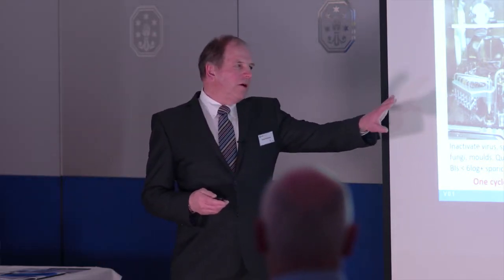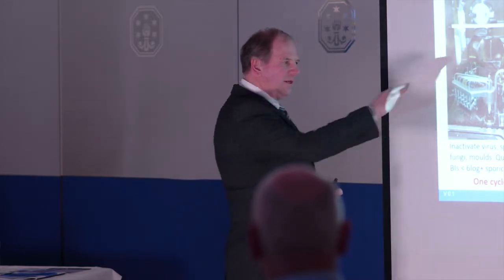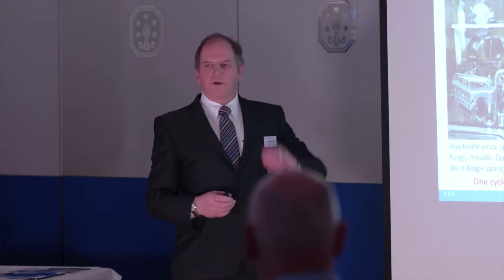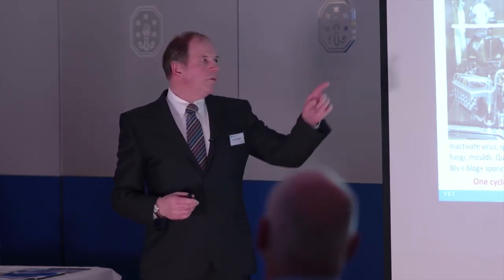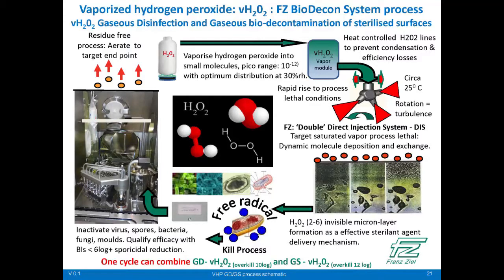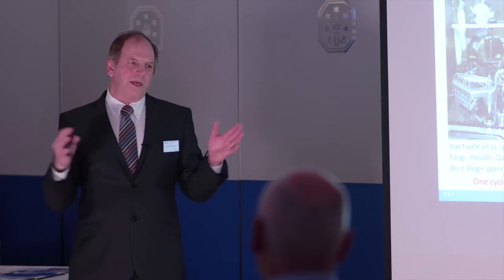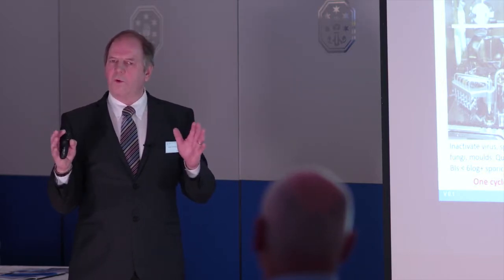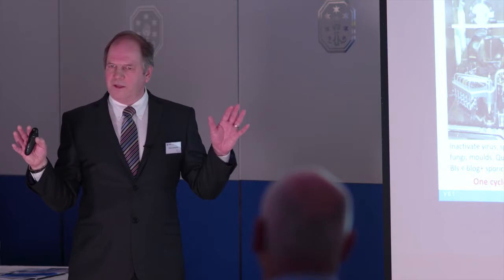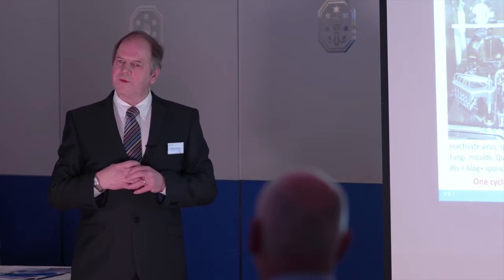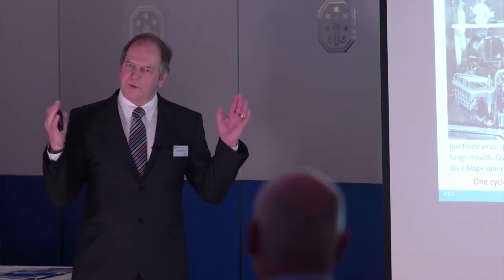We now need to go through this mechanism where we create the saturated vapor, we get the deposition, we get the free radical attack, and then the focus goes on to aeration time. Because with direct injection technology and some of the filling lines that we build now, 10, 15 minutes is normally the range for 6-log efficacy kill across the whole line. That's it done. By the time you get into the decontamination phase, you've got all those biological indicators done. Where the cycle time is longer, it will primarily be because of a gas distribution challenge, not because we haven't reached process lethal conditions.